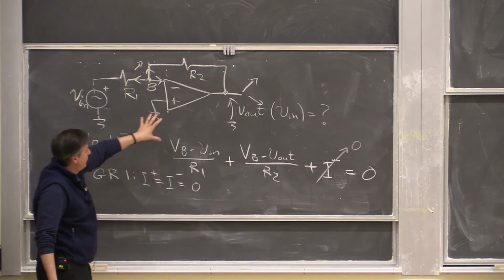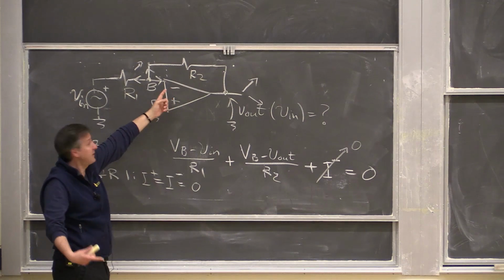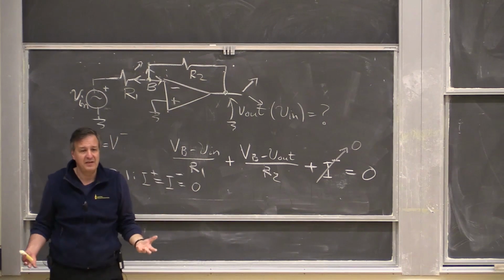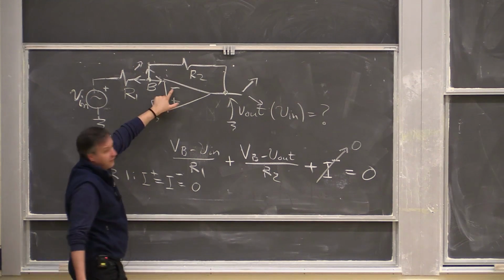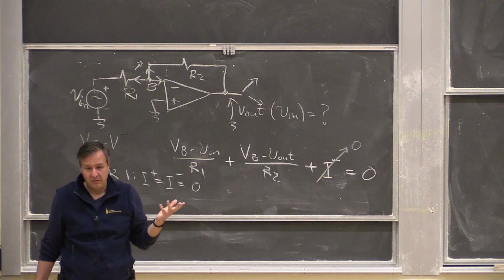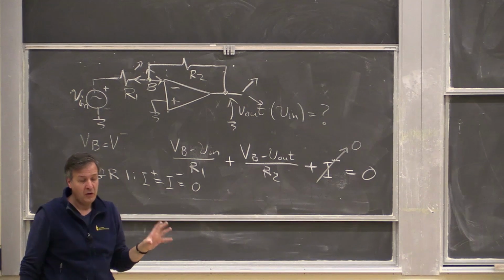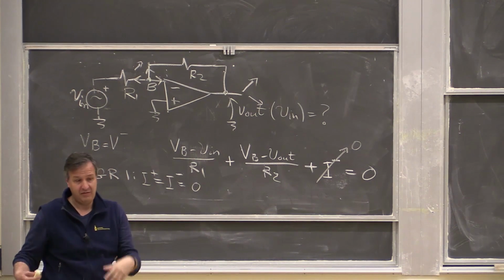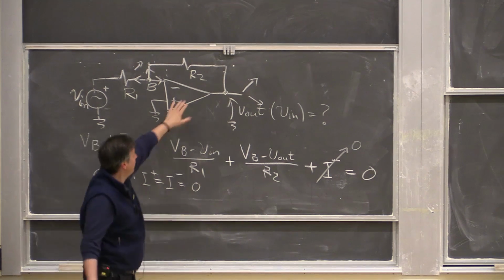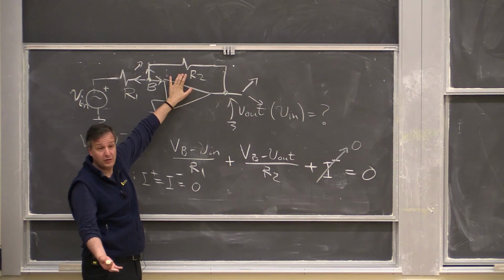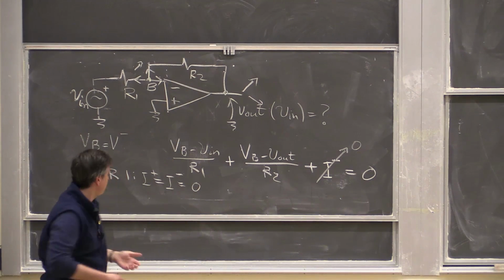In general, you can check negative feedback fast if the feedback element is just a passive element, a resistor, or a capacitor. If you're connected to the negative input, that is negative feedback. So you don't even need to check that. But I'll show you later the case where that's not the case. If you put an active element in the feedback, things can change. But by a passive element, I mean a resistor or capacitor. They will not change the sign of the signal coming back.